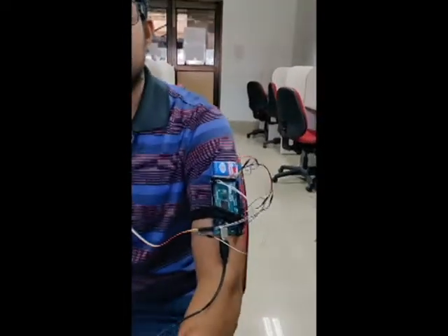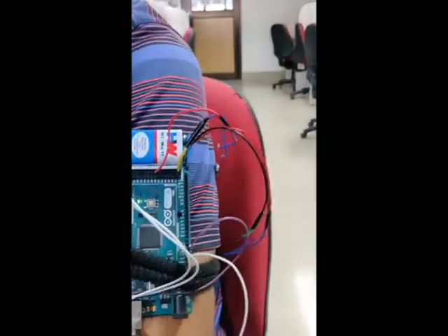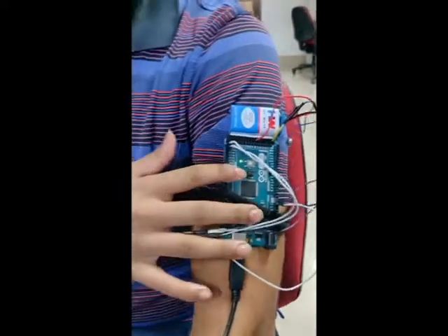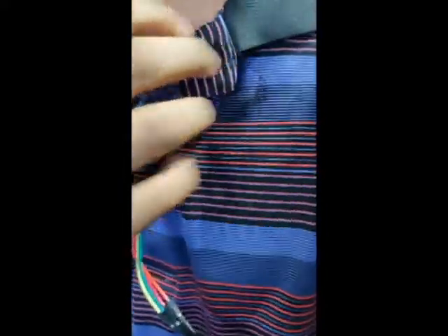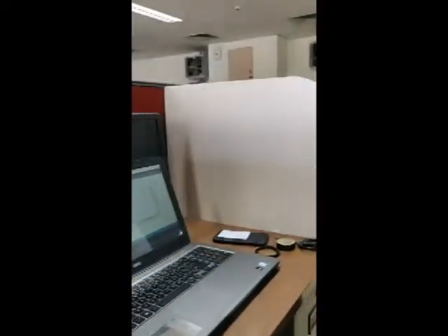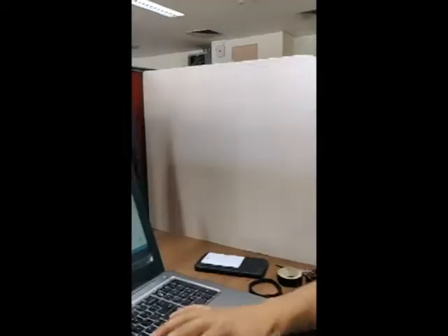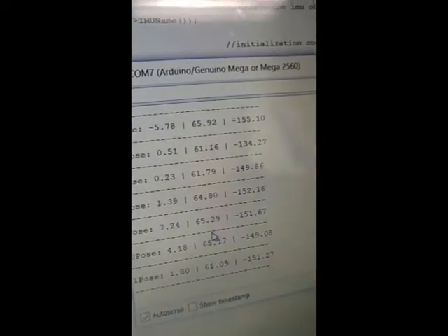Alright, so this is the accelerometer cum gyroscope implementation that we use to measure the posture of a person. The Arduino board would be connected to the person's arm, and the device, the actual MPU 9150, will be connected behind a person's shirt, fastened with a magnet. So what we're going to do is that when we run the program, if we look at the middle value here, that's the required value, and that's called the pitch, the inclination of a person. So right now I am doing okay. When I'm perfectly straight, the values will be around 55.